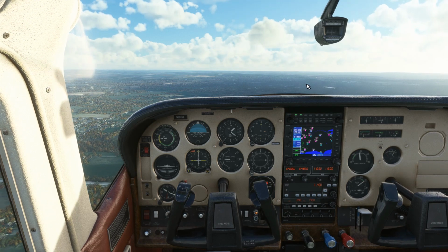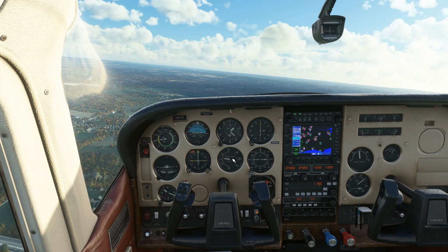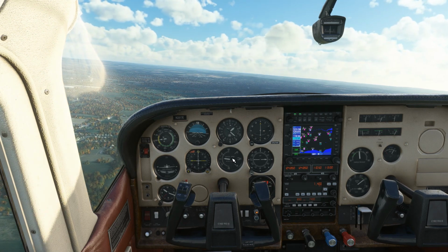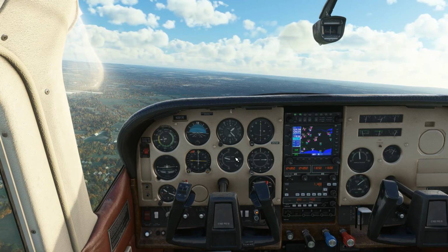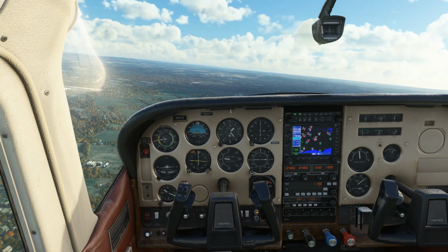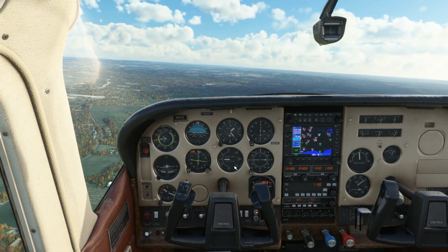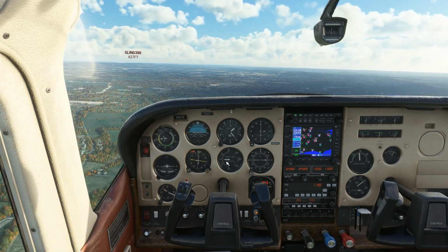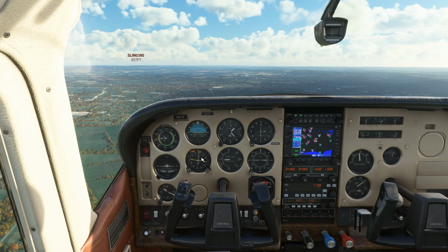I never turn left or right. You may see this deflect. So I may need to put in a little bit of trim just to keep that at 0 so I'm not climbing or descending. There we go. So I'm just putting in a little bit of trim there. And we're back to 0. So do practice that, and just keep an eye on your vertical speed indicator to see if you're climbing or descending, see what heading you're on.